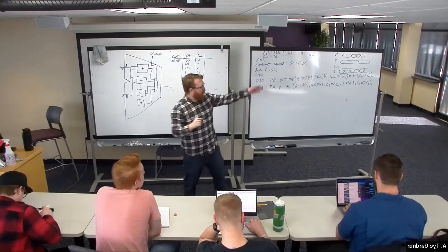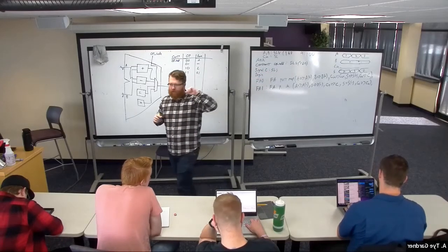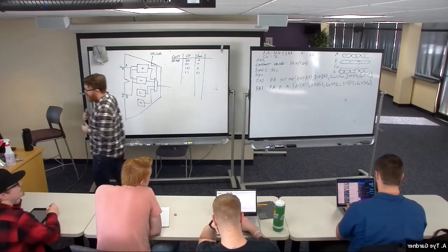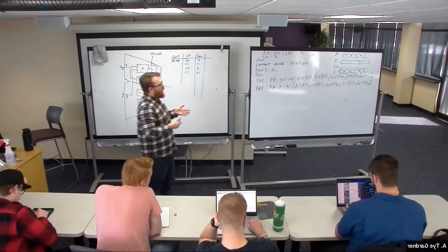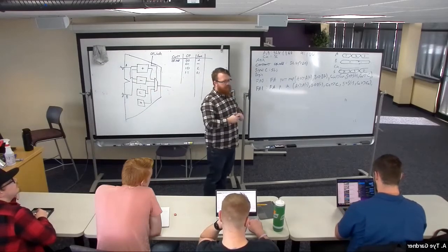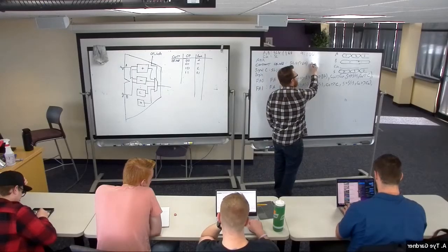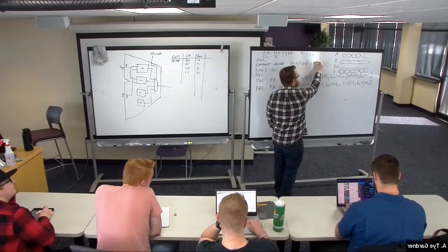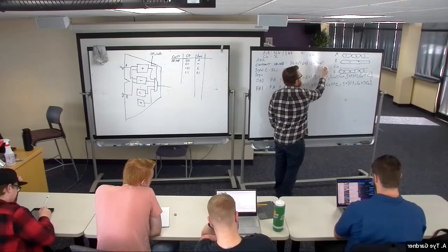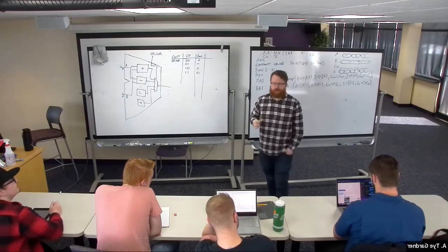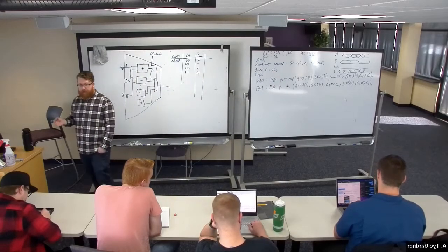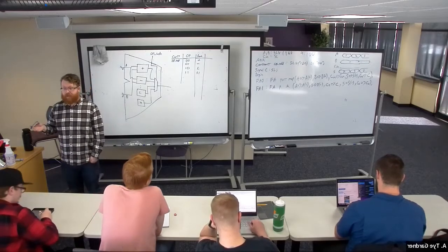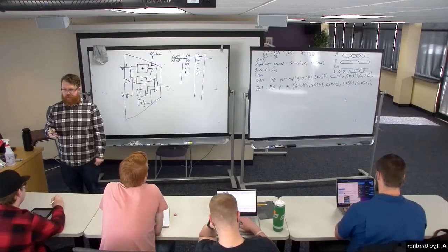Standard logic vector, SLV, is the abbreviation that I use when I write on the whiteboard. You can Google it if you're not quite sure what the right actual syntax is. Well, I'm not quite done, because how do I make op add have a value? I do this where I say colon equals 0, 0. Ta-da. Now when I write op add, it does 0, 0.